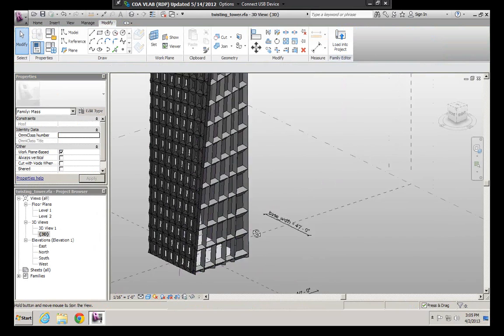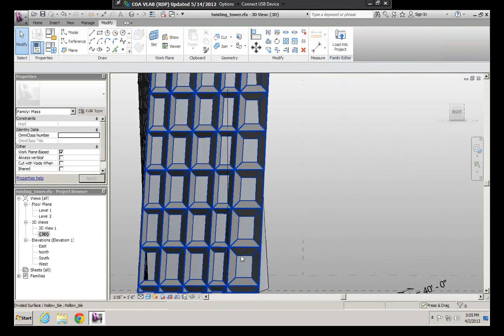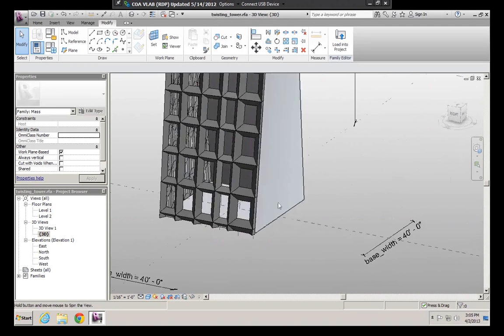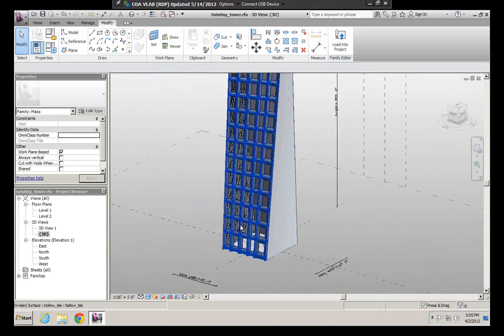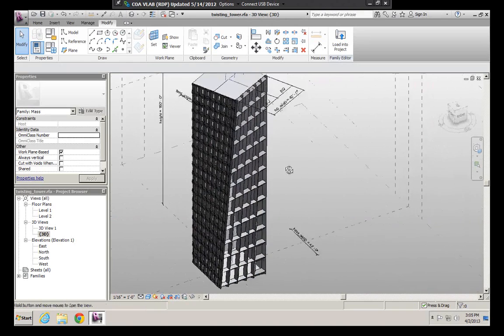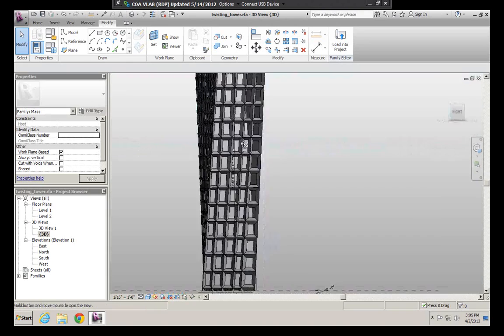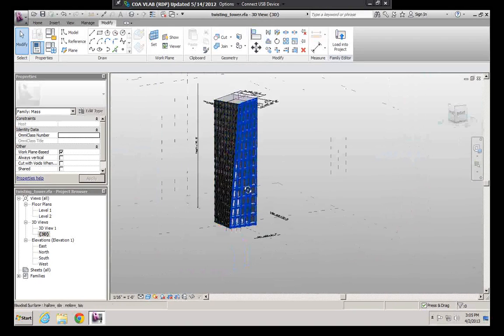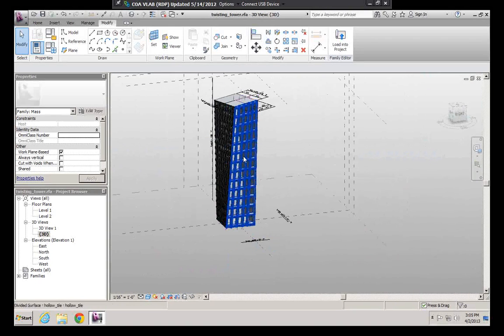And now it has calculated, and if you look closely you will see that the offset value for this tile is more than this one, because the area of this tile is larger than that one. So this is the strength of the adaptive component. So it's depending on the division, it will give me different size of tiles, and it's adapted to the surface curvature as well.